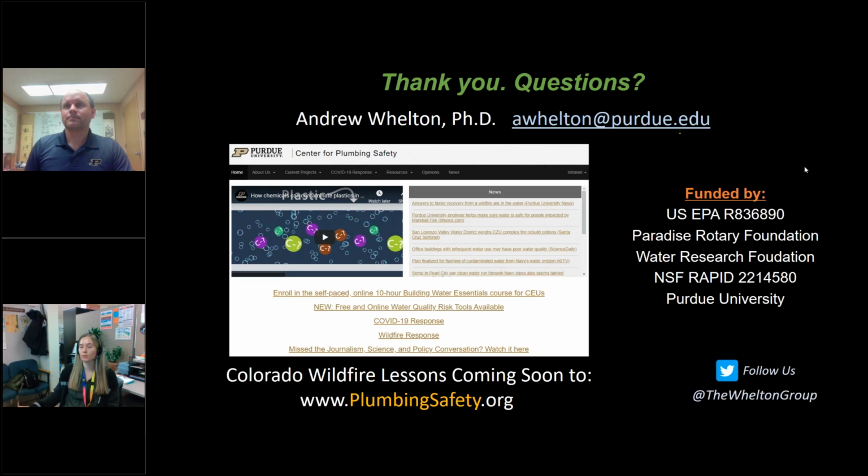So the first question was, at what depth do we no longer see wildfire damage to underground water mains? That's a good question, and there's a couple things. So first, if you have soil cover, ground cover, I think a new study came out recently by Oregon State University that indicated it's over 2 feet, 2 to 3 feet. But the thermal modeling that they applied assumed a certain fire of a certain intensity above ground. So if you have cars on fire versus timber versus just a forest burning, there are different thermal gradients that are subjected to that ground. And so I think the working theory is over 2 feet deep, you should be okay. I certainly wouldn't expect you to have thermal damage 6 feet below the ground with water mains.